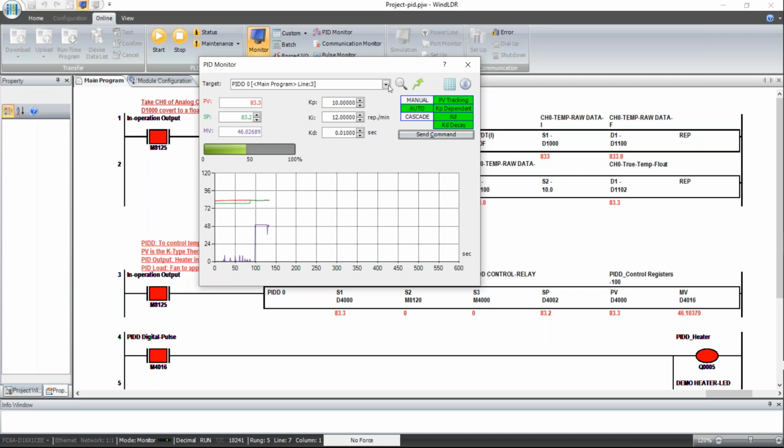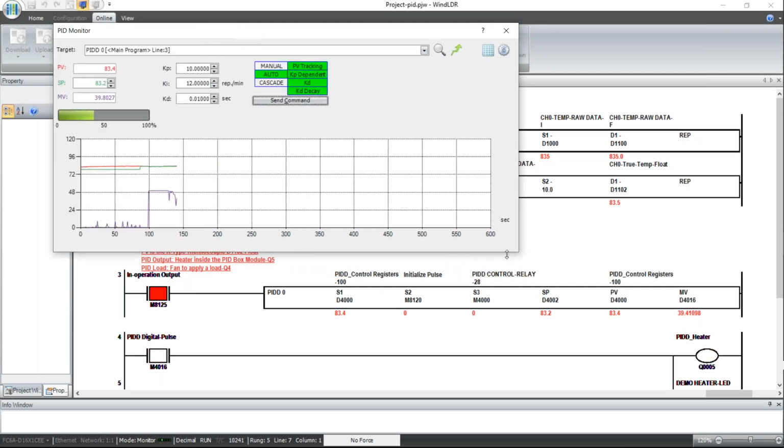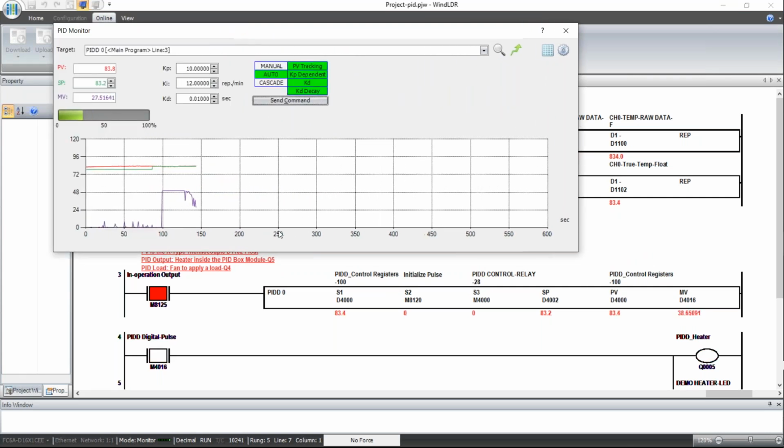So now, sorry, let me put this up for a second and let you look at it, right? Again, in here, the PID is taking my PID output, which is 0 to 100% decimal, and converting it to an SSR, or to a digital output, to make sure that the set point and the process variable are equal, right? They don't have any error.